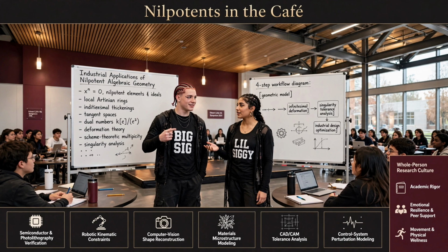Precisely. So step 2, the algorithm uses the nilpotent Lie approximation to calculate the exact admissible path, the highly complex sequence of forward, reverse, and steering angle adjustments that stays epsilon close to the thread. It calculates the optimal parallel parking wiggles required to perfectly track the physically impossible path. Exactly. And the literature contrasts this exact algebraic method with classical navigation, which used ordinary, Lissajous-like out-of-phase sinusoids. Basically just applying rhythmic sine waves to the steering column to make the robot wiggle blindly. Which is wildly inefficient and slow.